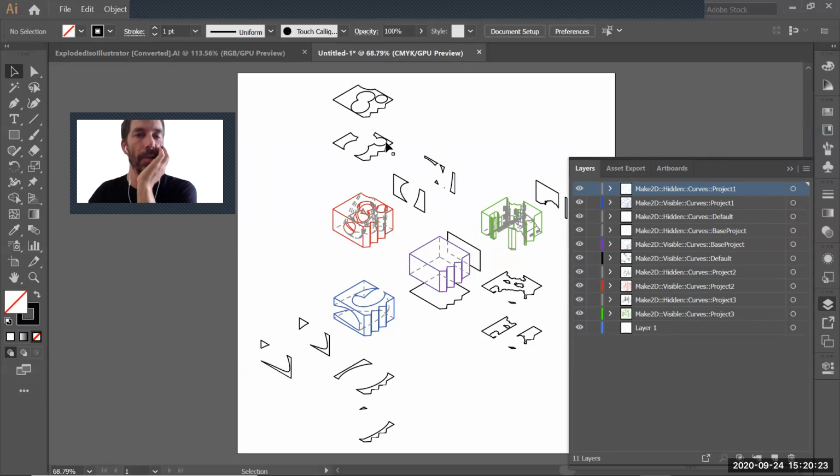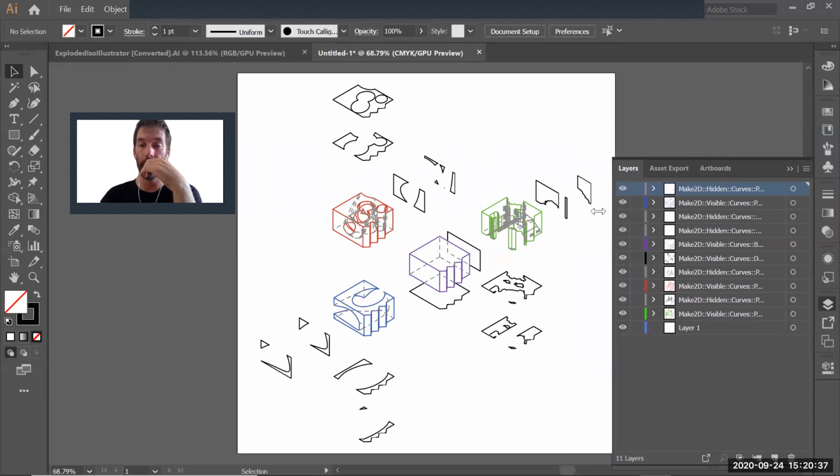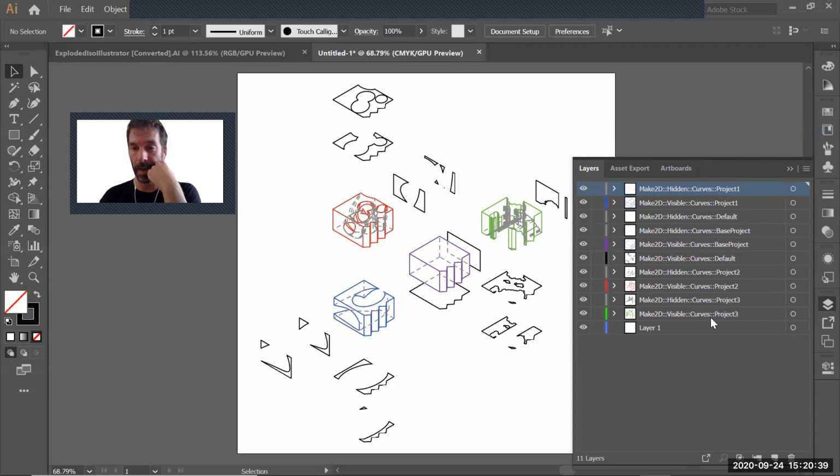Okay, you could have changed those as well in Rhino before taking them here and say, hey, this guy and this guy should be in a different layer, etc. But I don't think it's that difficult to change, because you can pretty much select them manually here. I recommend that you organize all of this a little bit first. I would place all of the hidden layers underneath, one by one, to make sure they're always underneath the visible ones, no? So the package of visible is there, and the package of hidden is there as well. Okay, now you can start selecting, no?